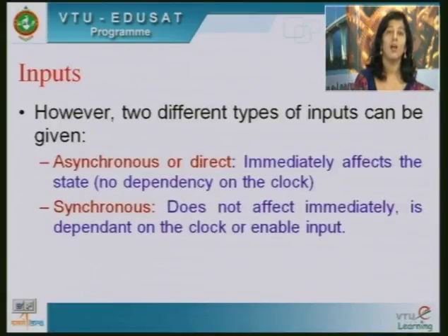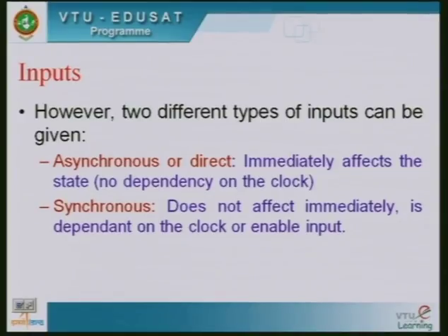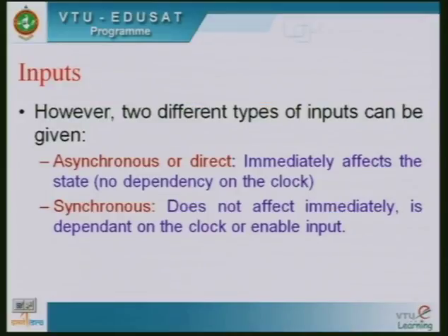However, it is possible to give inputs in two different ways. So, next we will design a latch, an extension of this basic element. The bistable multivibrator is the fundamental element which is used to make a latch and then a flip-flop. Now we are going to extend the concept of this bistable element and see how inputs can be added to this element. I can add inputs in two ways, either asynchronously or directly, and the other way is synchronous inputs.